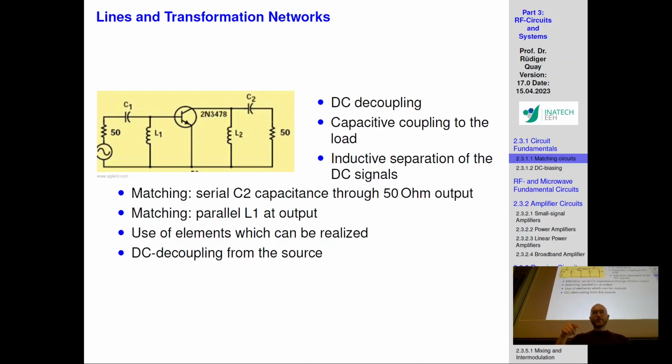And to apply the large signal voltage, you can't just transfer it through the air towards the device. It will not have it. So you need some sort of metallic conductor that takes it. And if you have this metallic conductor going to your device, and you're using the Cs to block it off, to decouple it from the other effects from other power sources, you also don't want your RF signal, your small voltage signal, to go there.